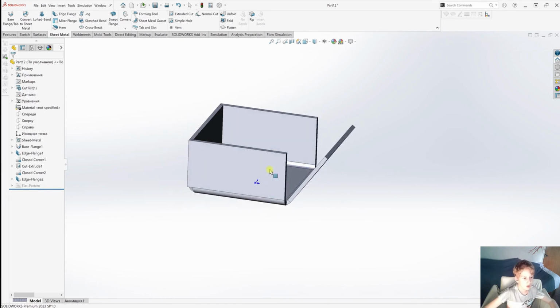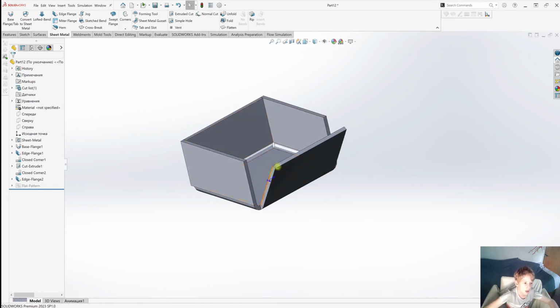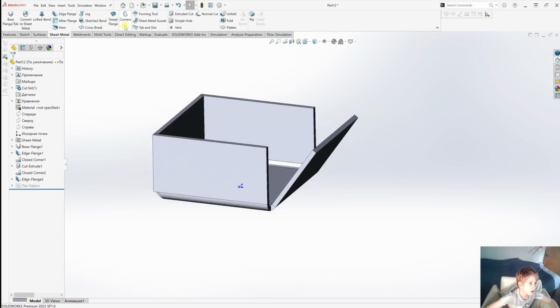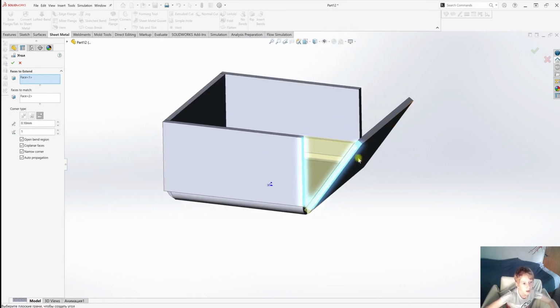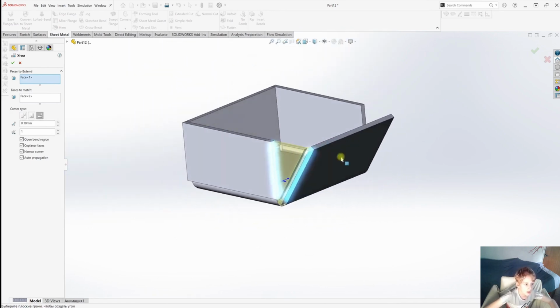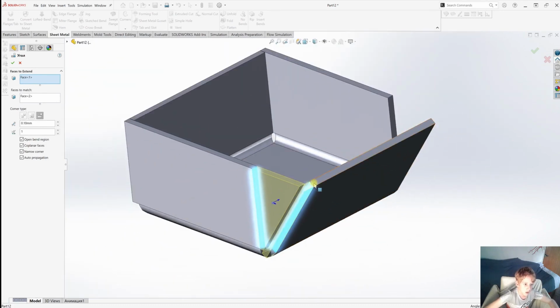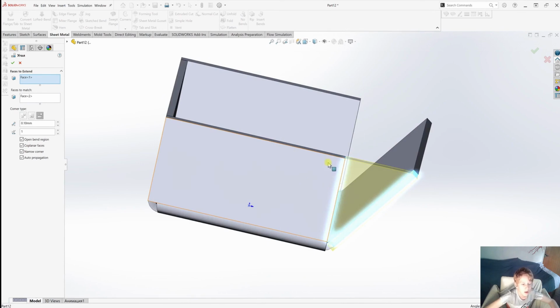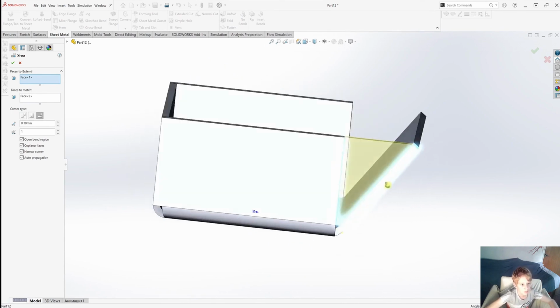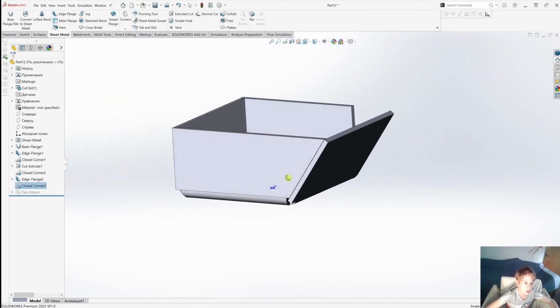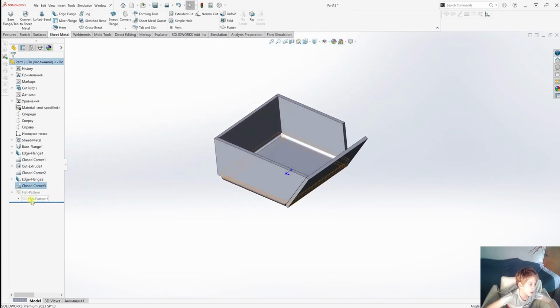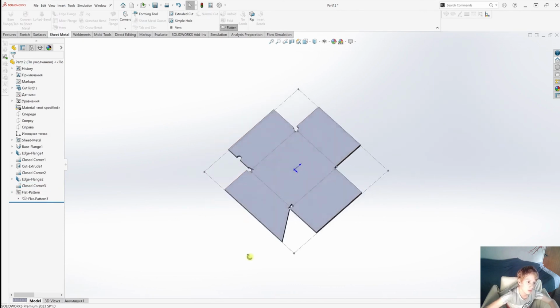After that, I will show you how you can use the angle command to close the gap between a beveled surface and a regular surface. With the angle command, we remove this surface, it will take a moment to process and then give us this result. On this side, it will extend the plate, and on this side, it will stretch it up to our plate. This results in a beveled angle. If we unfold it, this is what we will see.